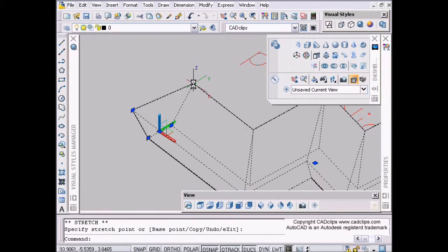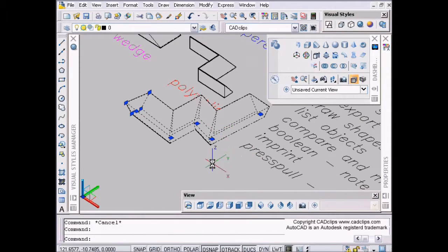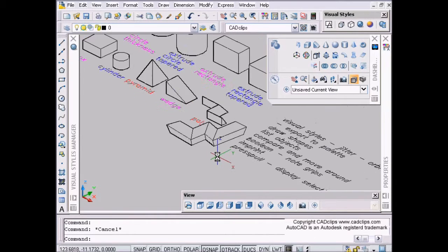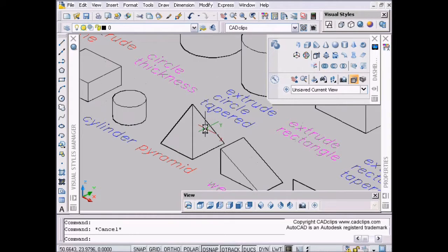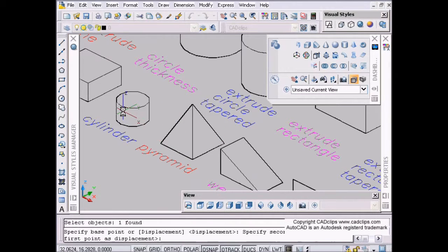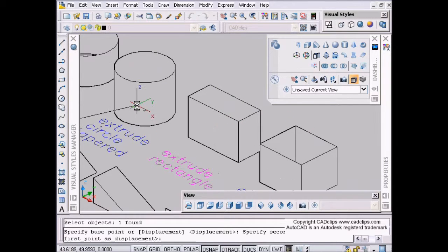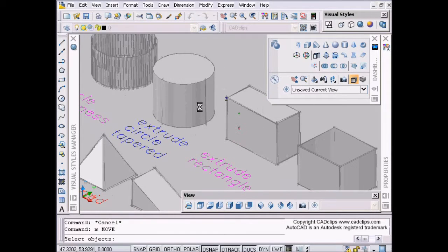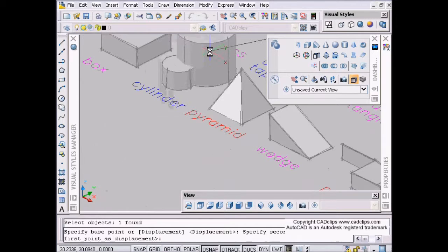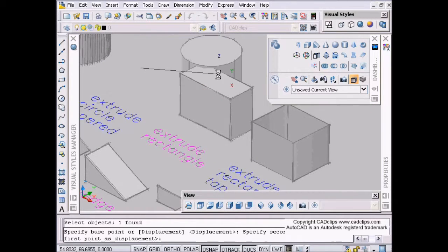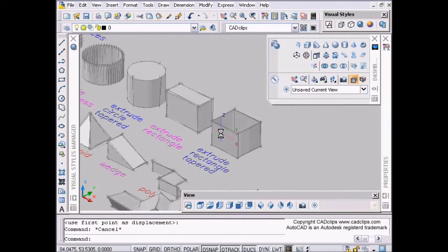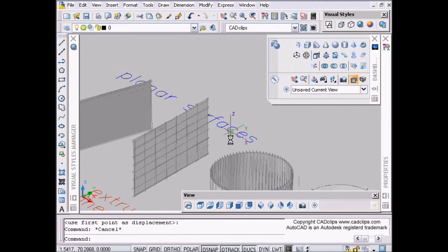And then with that polysolid, we can take those grips, and using our ortho, you can do all kinds of neat stuff like that. Shift middle mouse button after we grab it. Okay, start to use some of our Boolean operations. One of the things I like is if you take an object now in 3D and you move that around, you can actually see it reappear and disappear as it kind of blends its way through the surfaces, and you can do that in conceptual mode as well by taking these objects and moving them around. So AutoCAD 3D has come a long way with that. Okay, so there's a little bit on some different shapes.